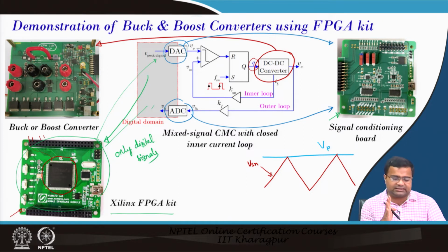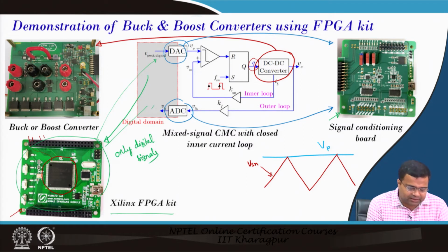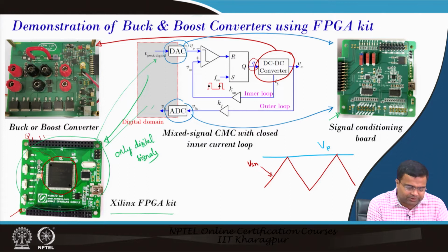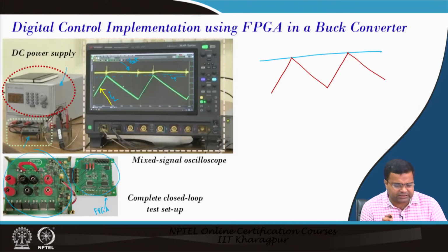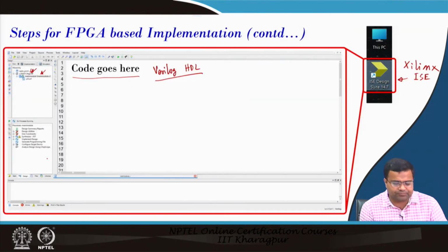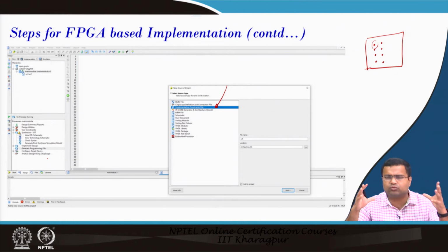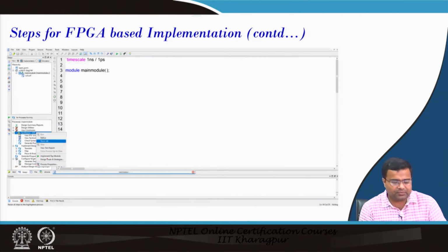So naturally the address of this pin will ultimately be reflected in the address of that pin, but it depends on how they are connected, what routing is used, and whether this pin is connected to that pin or not. That will be given. So you need the UCF file to clearly highlight the pin configuration and their addresses, and when we go to the actual implementation, we will show it.